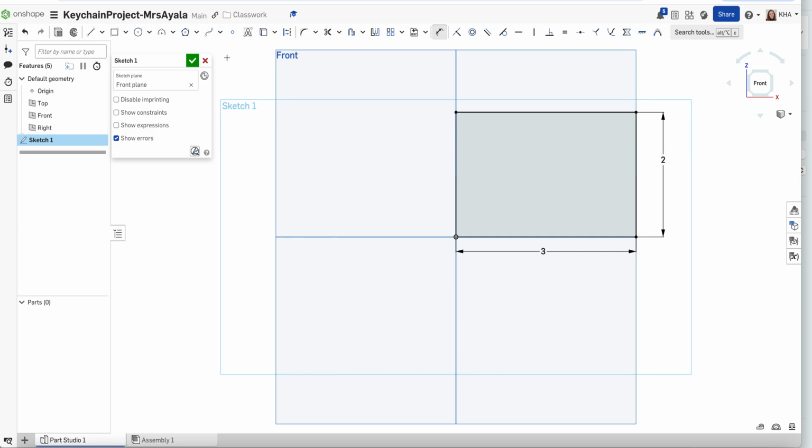Now that we have this part done, let's see, how do we make those rounded edges? This is called the sketch fillet. A fillet tool helps you round off edges. So I'm going to click on the 2 edges that I want to have this rounded intersection. I can click down. It's going to ask me what kind of radius I want this curve to have. So I think I'm going to keep it the way it is, 0.25. You can certainly edit it in your own case if you're working on this.